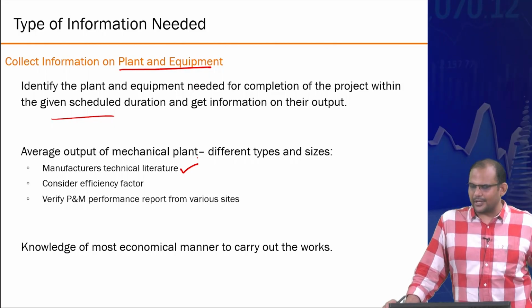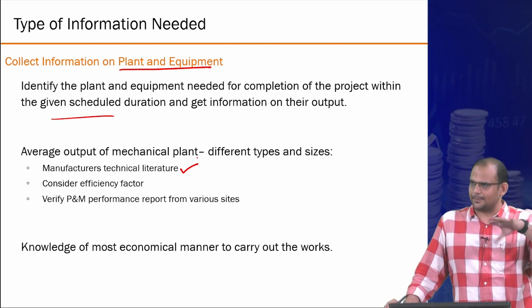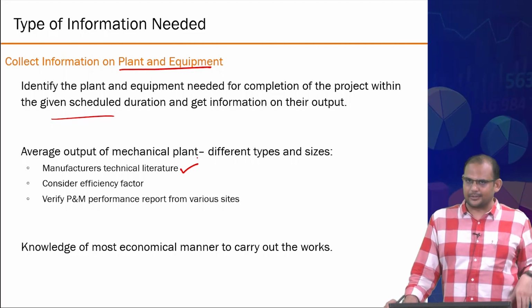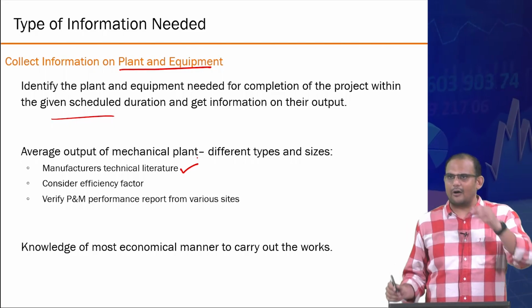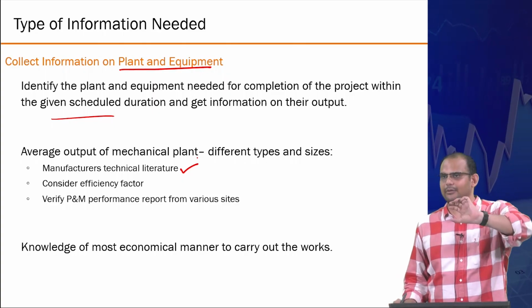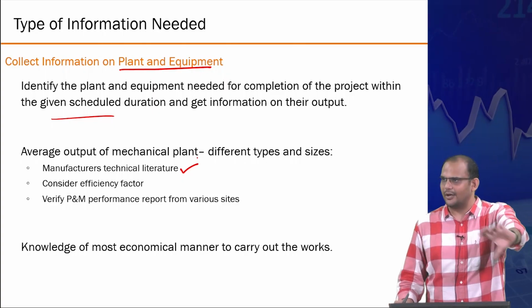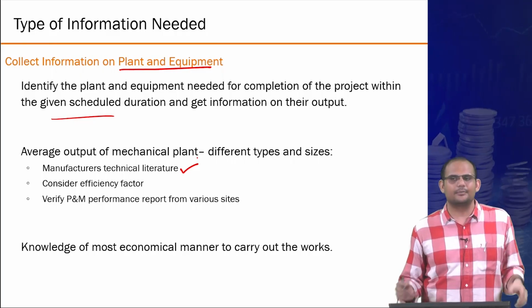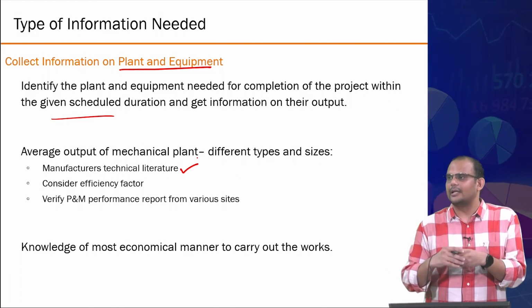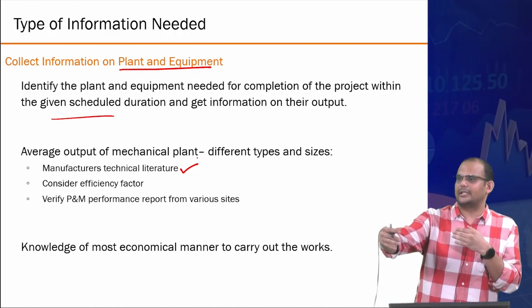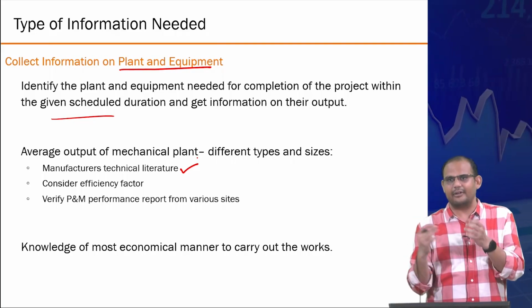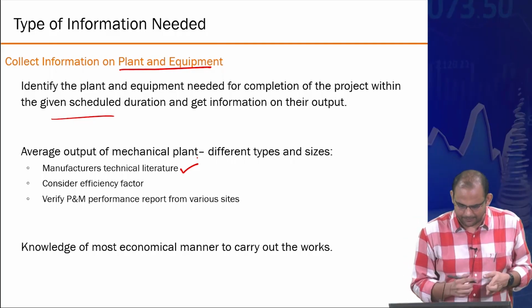When you buy a computer, you rely on the motherboard's speed and frequency, and all this information you get. Sometimes you may need to do that. For a crane, how fast can the wire actually move in a second, in a minute? All these are specified by the crane manufacturer in terms of the safe operating limits. Can you really move faster, or can you make it really slow? All those things you need to know. What are the ranges? Otherwise, you'll not be able to estimate it properly.